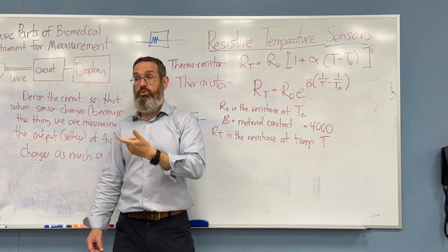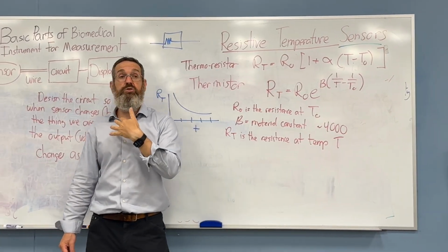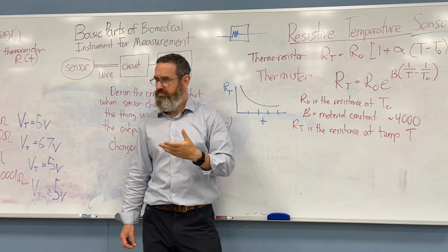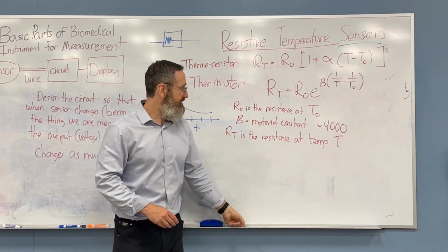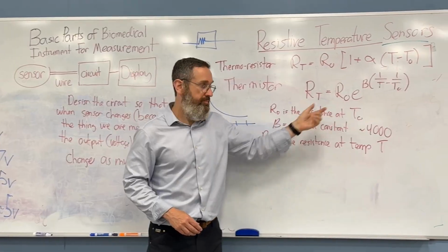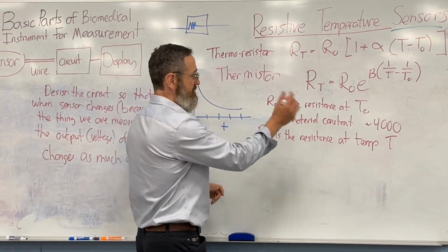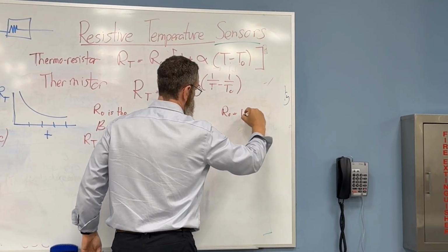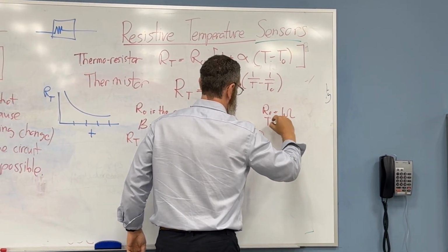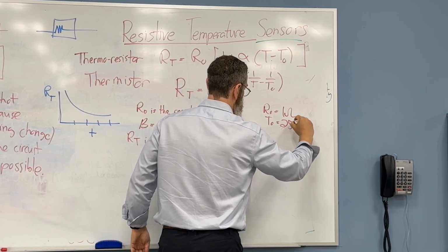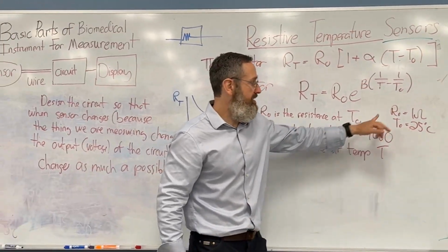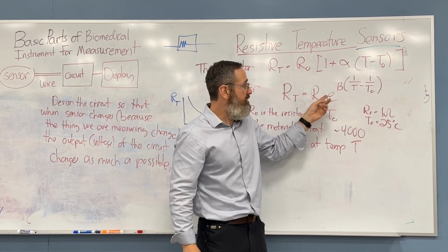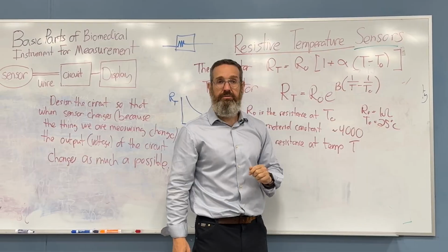But as a general rule, for the applications that we're going to be interested in, we're going to be using thermistors. Okay, so now you are given a thermistor. Let's say R0 maybe is, again, 1 ohm at 25 degrees C. Doesn't have to be. It could have been 10 ohm at 37 degrees C. This shouldn't bother you. These are just the constants that you plug into here.